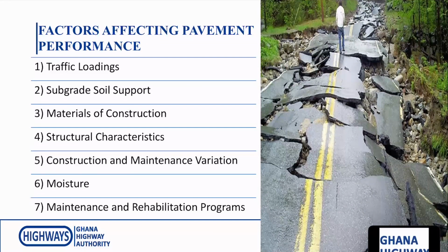Now, the next point to consider are the factors that affect the performance of our road pavements. And these are traffic loadings, subgrade soil support, material construction, structural characteristics, construction and maintenance variation, moisture, maintenance and rehabilitation programs.